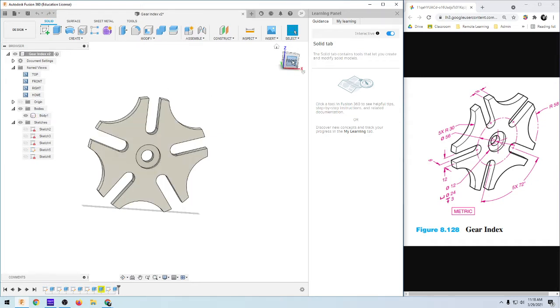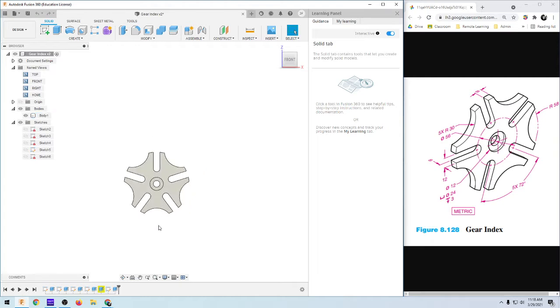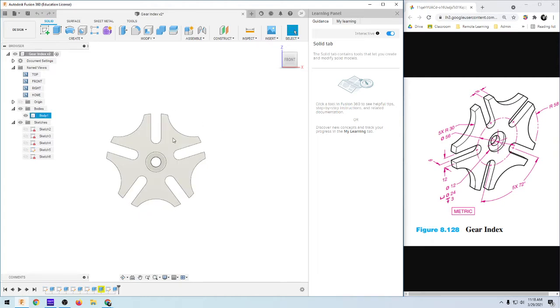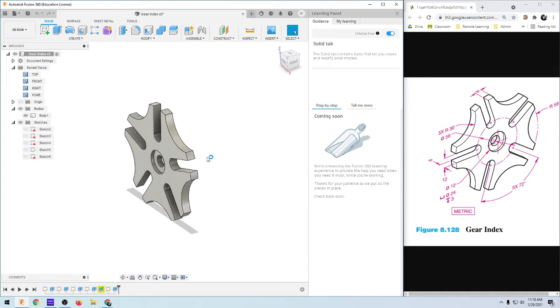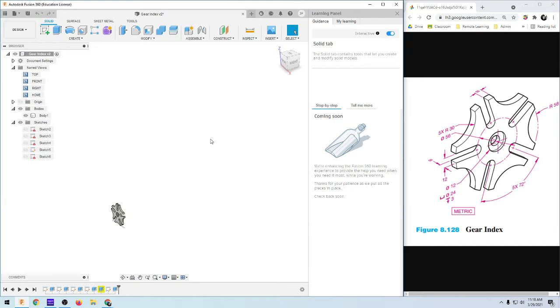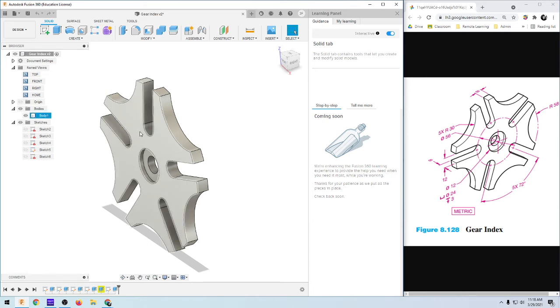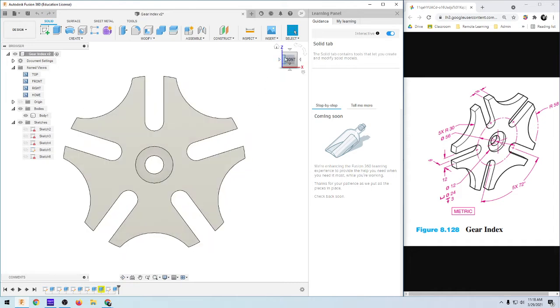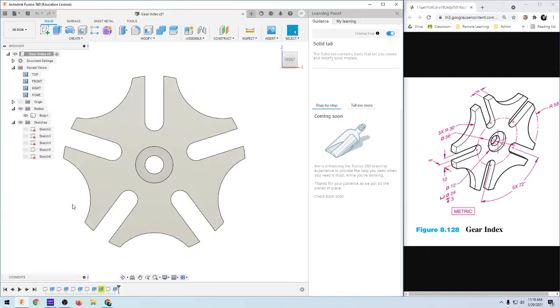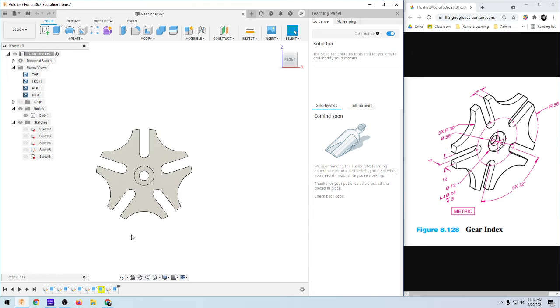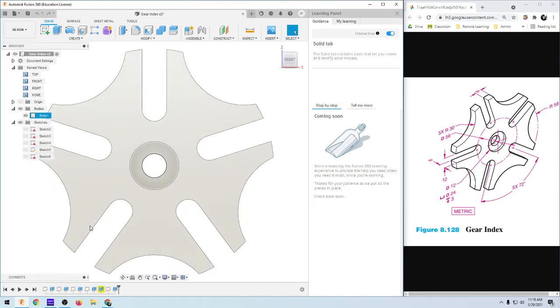So from here, there's a few hotkeys that I want to tell you about that are super convenient. So if you're at a weird view like this, right? If you hit F6, if you like zoomed out and you're over here and you can't really get in there, you're just going to hit F6 and it's going to zoom in. It's going to fit the part to the screen, and then you can also just click this cube. Just like how SolidWorks and Onshape work. So that's pretty cool. So F6 was that hotkey just to bring it in.